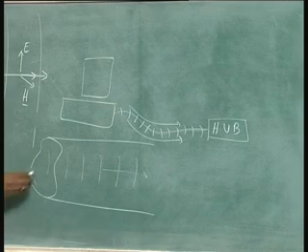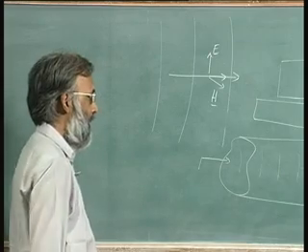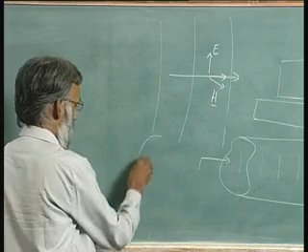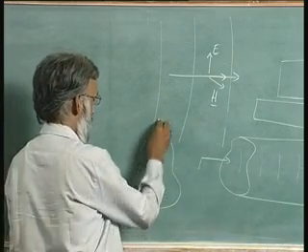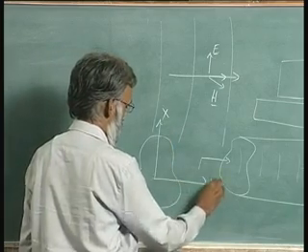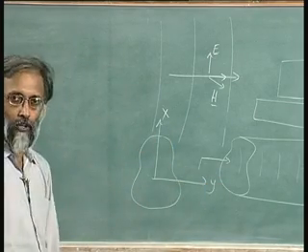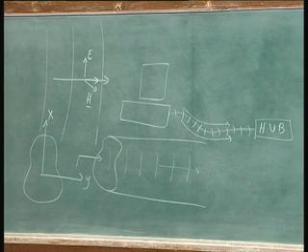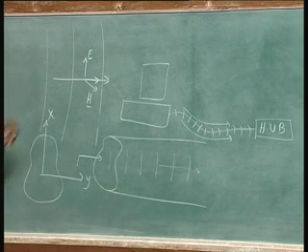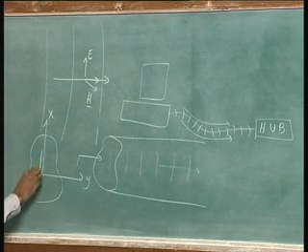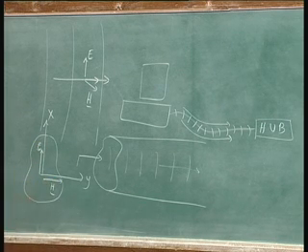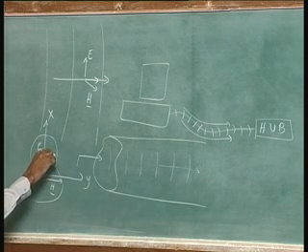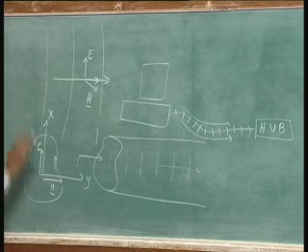Let us look at this along the axis. So, it has got some shape. This is x, this is y. So, this pipe has some cross section. Now, my electric field and magnetic field are what they are. So, let us say I have my electric field this way and my magnetic field is this way. Now, you can see that there are places where the electric field will be tangential to the wall.